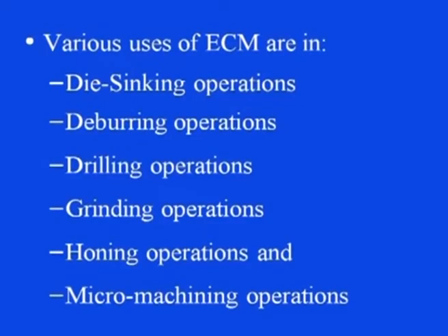Now, let us see the uses of this ECM process, what are the different applications where this can be effectively used. For die sinking operations, for example, for deburring operations, for drilling operations, for grinding operations, for honing operations, for micro machining operations, this process is found to be very effective.